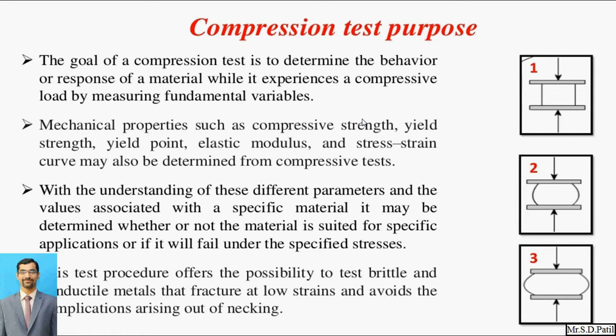Now why is the compression test carried out? The goal of the compressive test is to determine the behavior or response of the material while it experiences a compressive load by measuring the fundamental variables. So basically this is the first purpose, the response of the material under the compressive load.